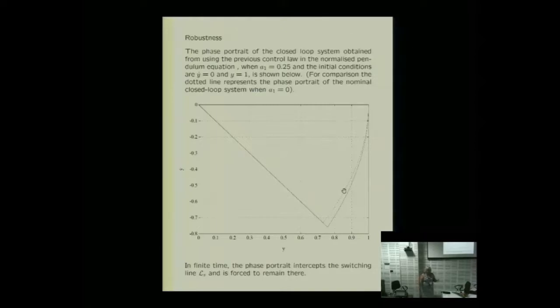Why is it different? Well, it's different because the dynamics are subject to the sinusoid. So the sinusoid is present. It hasn't reached the sliding mode. We notice it reaches the sliding mode at different points, but once each of those entirely different systems has reached the sliding mode, they exhibit exactly the same dynamics: y dot equals minus y, fundamentally. So the sinusoid is completely rejected.